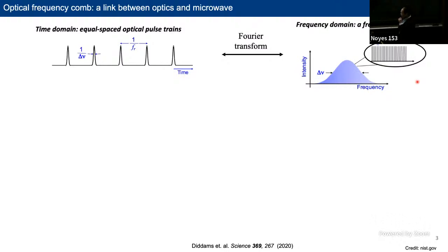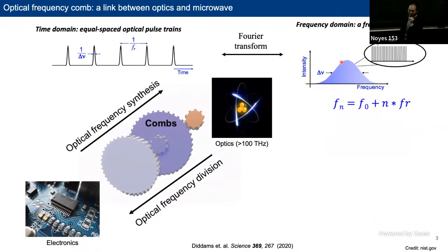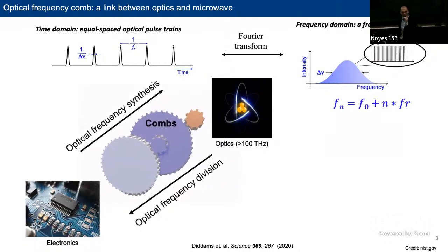And why is this kind of optical frequency comb so important for modern photonics and optics engineering? One reason is that the optical frequency comb serves as the bridge between electronic frequencies and optical frequencies. How do we understand this claim? The optical frequency comb is located in the optical domain, which has a carrier frequency of roughly a few hundred terahertz, and if you talk about visible, it's even higher. The spacing between adjacent comb lines is typically on the level of megahertz to gigahertz.